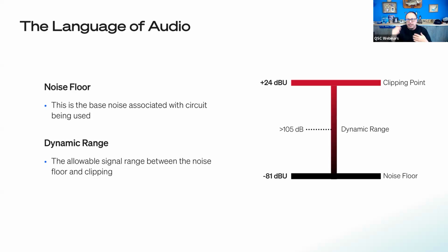It's going to, when it gets clipped down, you may be overdriving the inputs, you may cause some distortion. Every analog device has some sort of noise associated with it, right? Even if it's just an open input on the back of a processor in a rack. Now, you could mess with that and plug a wire in and use it like an antenna, and you could see, if you experimented with it, how that level would go up.